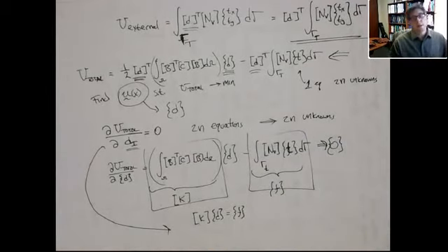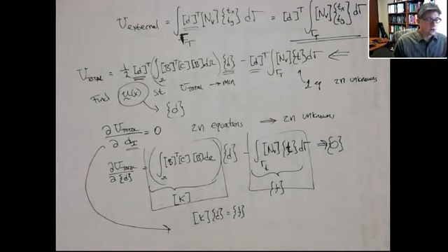So what that means is for any element where we can write the B matrix, and then we can write this NV vector, and then given a prescribed traction, you can integrate over the element and come up with the stiffness matrix and also the external force vector. You don't have to worry about doing these sort of ad hoc approaches like summing the forces at the nodes like we did for the bar element. Okay? So that's where those equations come from in the book.